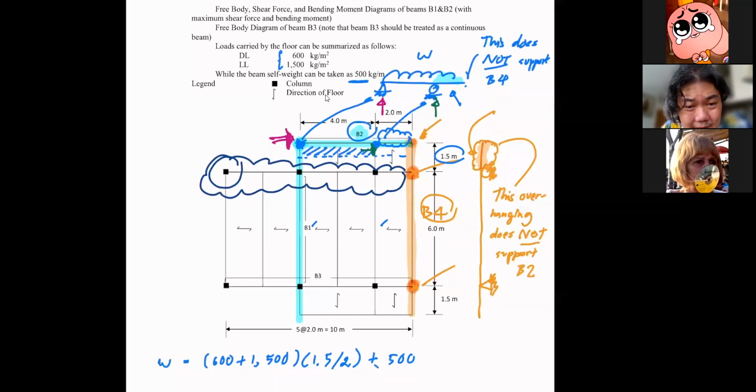I have a question: both overhangings are at the same level and they are connected. They are at the same level, and construction-wise they are connected, but they don't take the load from each other. You don't need to leave a space there for them not to carry each other. When under construction, you just need to make them connect.